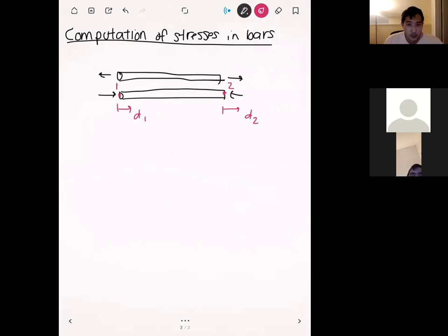From this, we can actually compute the structural stresses that are felt inside this element. Structural stresses are often something you're interested in if you're designing any kind of structure that's going to be loaded with forces or pressures. If you remember from your strength of materials class, the stress ultimately determines how much a member displaces, and it will tell you whether the structural member will fail and break apart. So when performing finite elements, you often want to solve for these stresses because that tells you whether your structure is going to break or not.